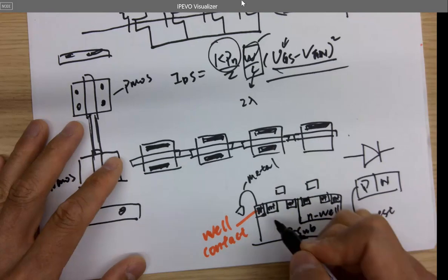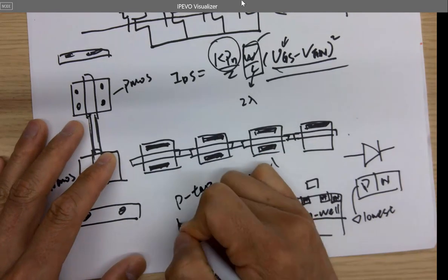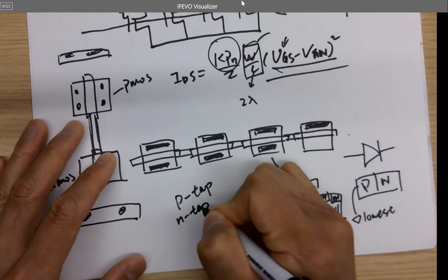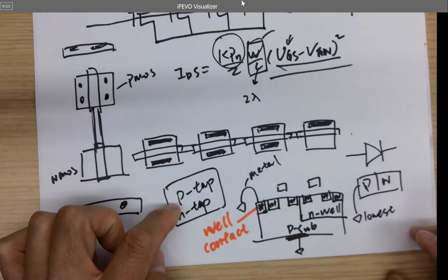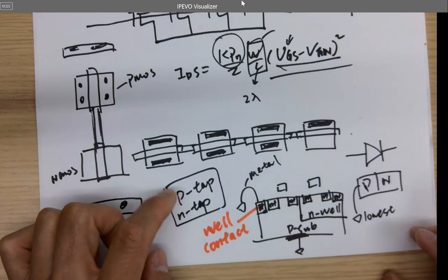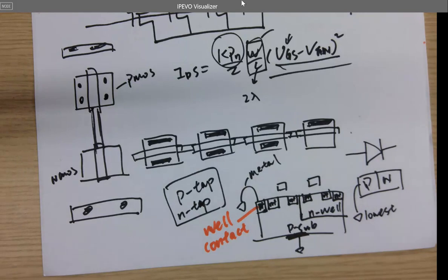So for this one, it's called P type, and for this is N type. When you are using Cadence, you can find that the components in the library have different names. A lot of times it takes you a very long time to find the correct one. If you have a lot of experience with different technologies, you search like N well, P well contact. If you couldn't see it, you start searching for N type, P type.